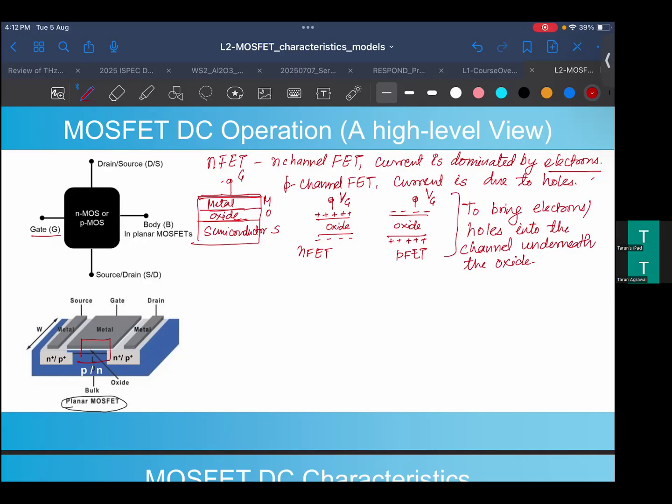And now what is the FE, which is called field effect transistor? So FET is your field effect. Now we have done the charge. Now how do we get the current from the charge? The charge is not going to flow towards the metal or the gate, because there is an oxide stopping it. That is like a big barrier because it's an insulating material. So then the charge would go in this direction, and that is what you would see in a MOSFET.